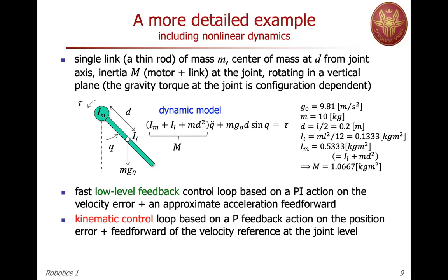So last time we commented on the need for a control loop for executing the desired motion of our robots. We assume that we have made a smart planning of the trajectories, either in the Cartesian space or in the joint space. Then we mentioned that in order to reproduce this in practice on the robot itself, we need to close some sensory feedback. So the minimum requirement is to compare the desired motion with the actual motion as sensed by your sensors.